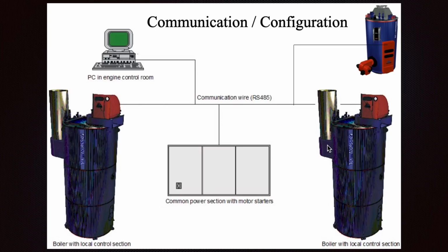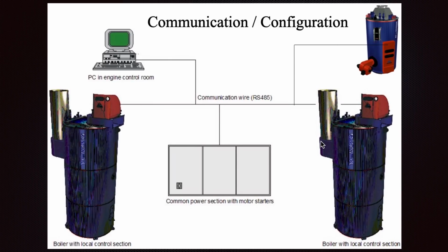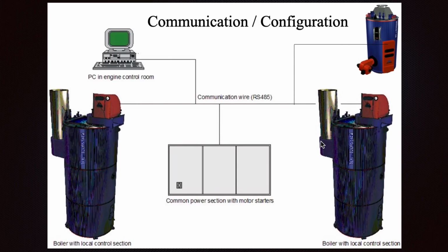Sometimes it's better for the boiler to run in slow mode, if you have such consumption, than to keep stopping and starting, because you will prevent your burner from getting dirty from the starts and stops, and also your fans and all the equipment associated with the fuel supply will run stable without a lot of adjustments up and down. But also, the starting and stopping of the boiler is always a check of the system.